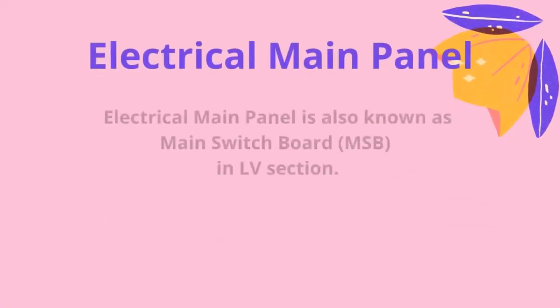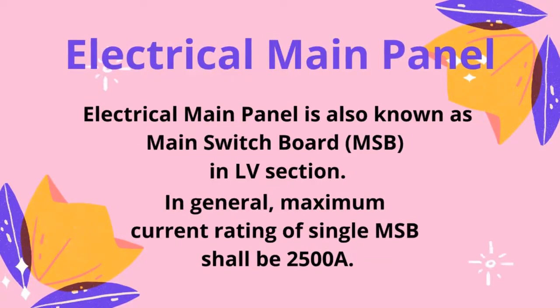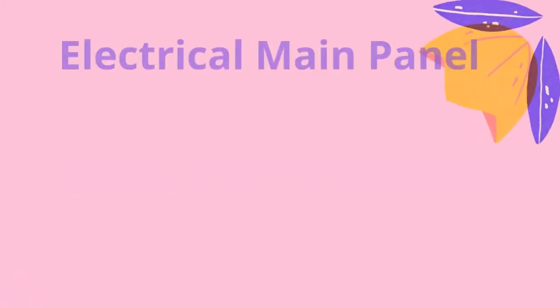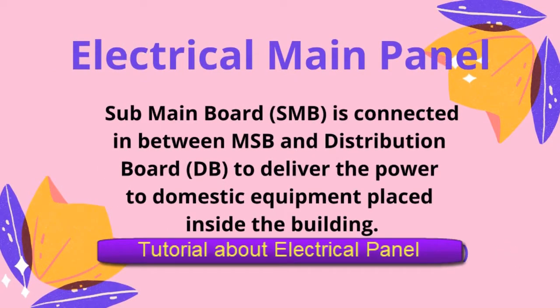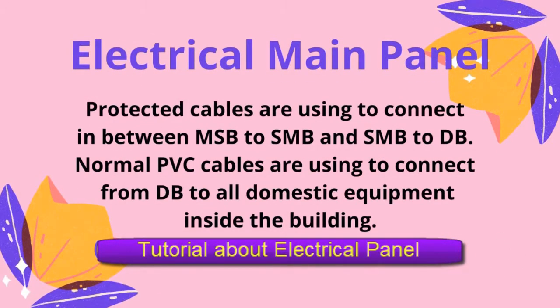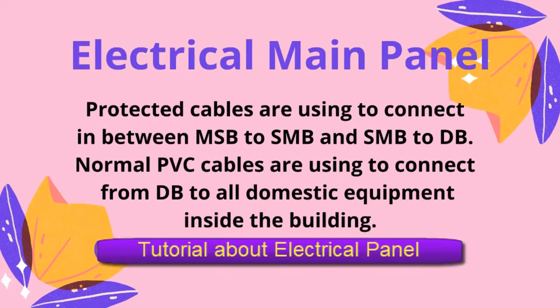The electrical main panel is known as the main switchboard in the LV section. In general, the maximum current rating of a single MSB shall be 2500 A. The sub-main board is connected in between the MSB and the distribution board to deliver the power to domestic equipment placed inside the building. Protected cables are used to connect between MSB and SMB to DB. Normal PV cables are used to connect from DB to all domestic equipment inside the building.